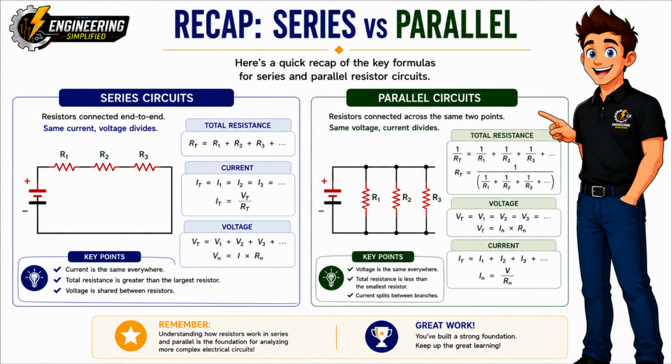Before we move on to mixed circuits, let's quickly compare the two circuit types we've learned. On the left are series circuits. In a series circuit, all the resistors are connected end to end, so there is only one path for current to flow. That means the current is the same through every resistor.